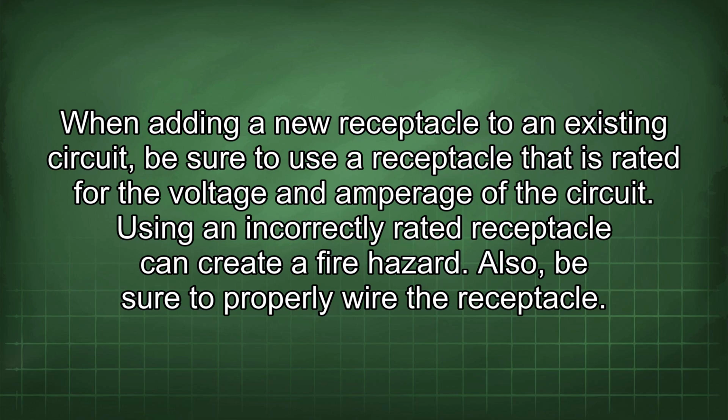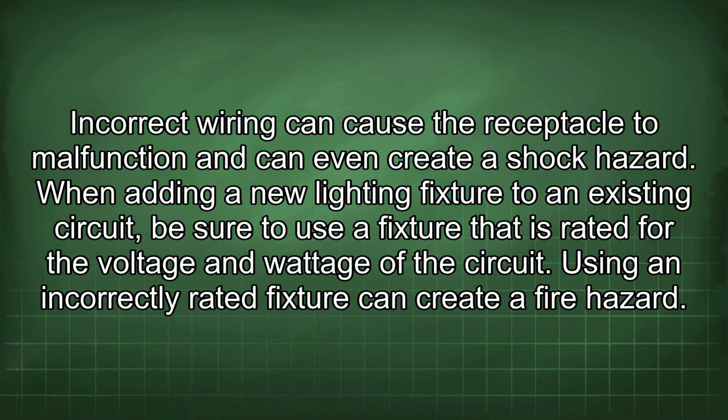When adding a new receptacle to an existing circuit, be sure to use a receptacle that is rated for the voltage and amperage of the circuit. Using an incorrectly rated receptacle can create a fire hazard. Also, be sure to properly wire the receptacle. Incorrect wiring can cause the receptacle to malfunction and can even create a shock hazard.